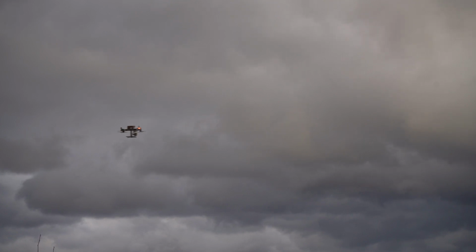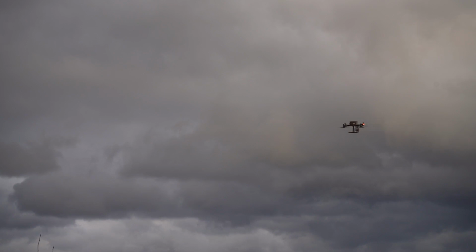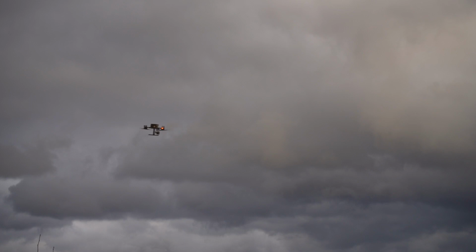For this process, the drone will need at least 30 meters of open airspace in front of itself. It is recommended that obstacle avoidance is switched on to reduce the risk of an incident. Once the IMU calibration procedure is complete, the data capture can begin by using the record button on the right-hand side of the interface, very similar to recording a video.